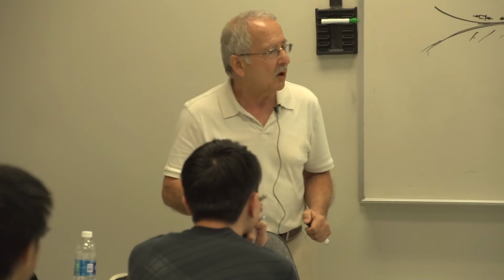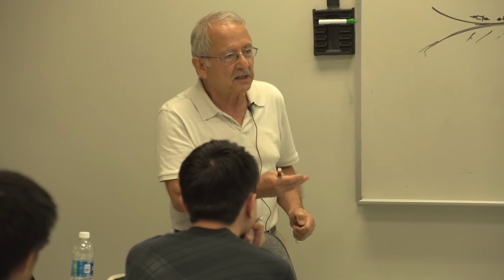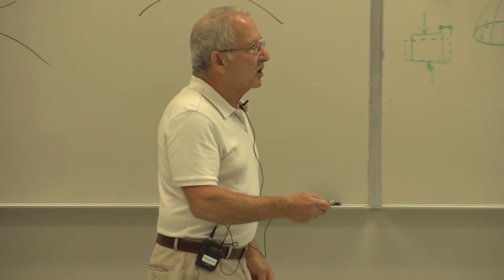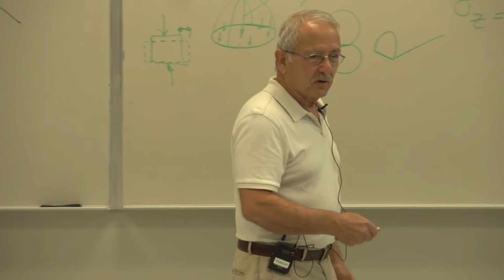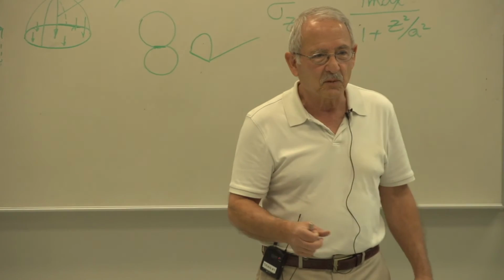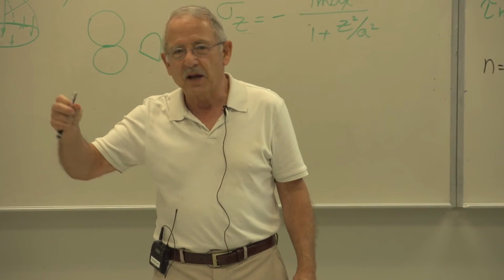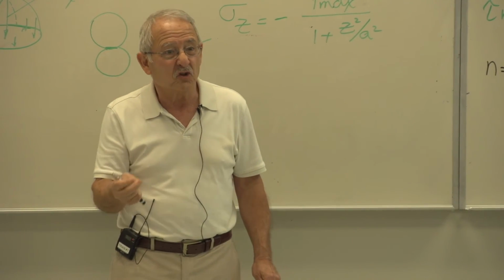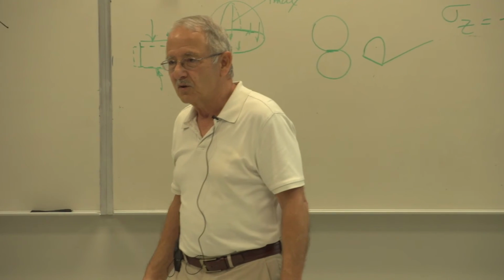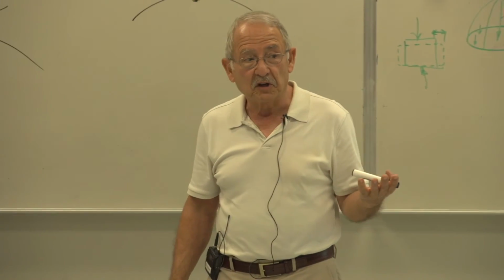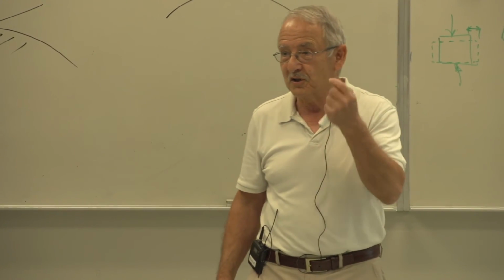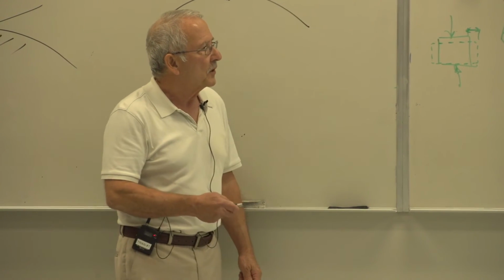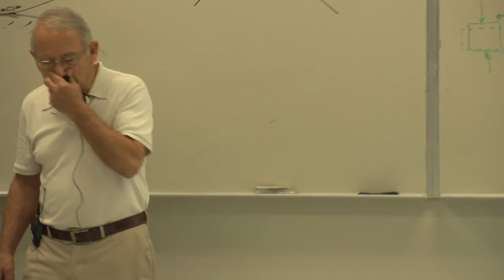No, it's not exactly. Although these stresses do exist exactly there, their magnitude isn't that much. Here we're talking about two very hard materials, not rubber, for example. And as you will see in an example problem, the area of the contact patch is minute. The radius is thousandths of an inch rather than inches. So even though the load may not be very large, the stress is very high because the cross-sectional area is very small. Okay? We'll see that in an example. So that's what we get here.